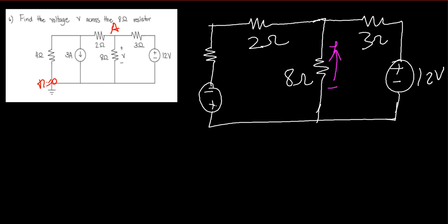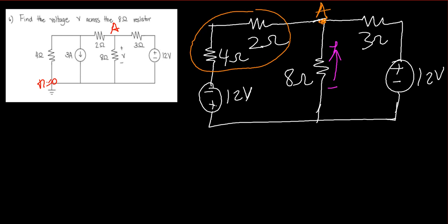This voltage source will be equal to 4 ohms times 3 amps, which gives 12 volts, and here the resistor will be 4 ohms. For this one, we can compute the equivalent resistance of this other branch and have something very simple to apply the Millman theorem at that junction that we set A.